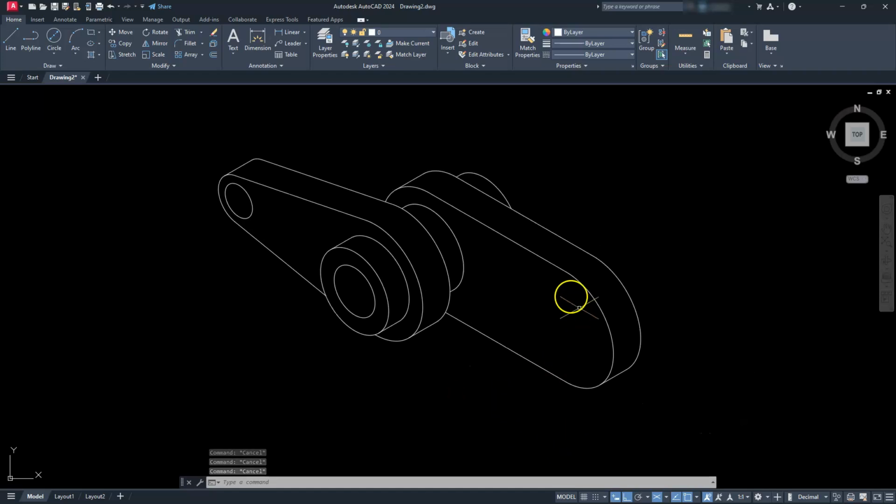And then finally, let's go ahead and put our little bump out that we have going here and also showing on the back side. So I'll go ahead and switch to isometric left again. Choose EL, enter, I, enter, go right at this center here. And then this one has to be a diameter, right? So D, enter. And I'll type in the diameter, which is going to be 60. Hit escape.